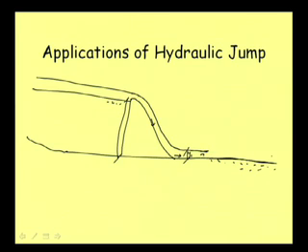Now, if we do not do anything in the downstream part, this high speed water will move for a significantly longer distance, and then will cause damage to the river bed. And suppose it is eroding all these things, then this eroded material will be carried downstream, and somewhere it will be deposited at the downstream. That will create another problem.